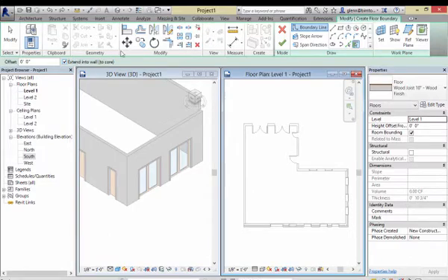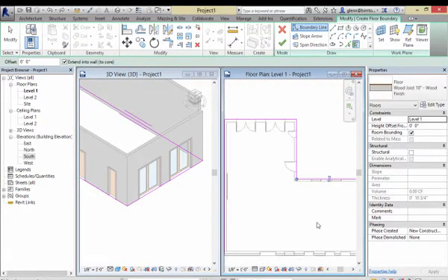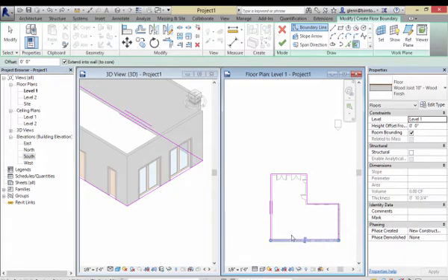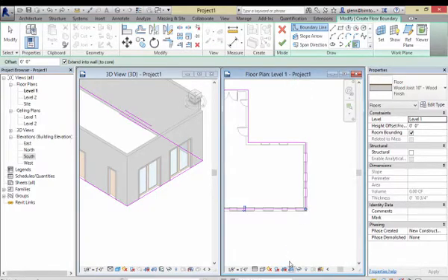So let's go ahead and put a floor in here. I will pick the walls. Notice when I'm picking the walls, it sort of guesses the inside of the core. I'm going to flip it so it's the outside, because cores have an inside and an outside too. I'll pick that wall, this wall, this wall, this wall, and that wall. I'm getting them all. You might notice that on these brick walls down here, the core is a little bit further in. The brick is a much thicker exterior layer than the other walls, but that's okay. It's all going to the face of what's considered the core.